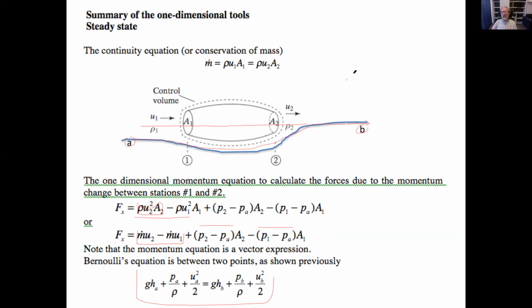You have a vehicle, and the flow goes around. You can go pretty close to it and pick point A and point B, and you can apply the same rule. But as I mentioned, if there is flow separation here, you cannot have point B here, because now we have flow separation and there is friction associated with that. We'll clarify these things more and more, and then we're going to use that later on.